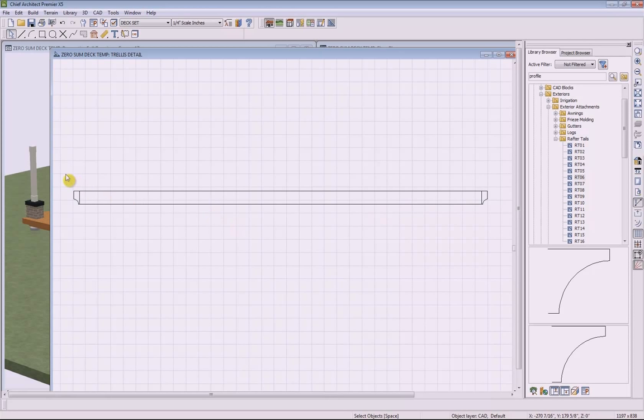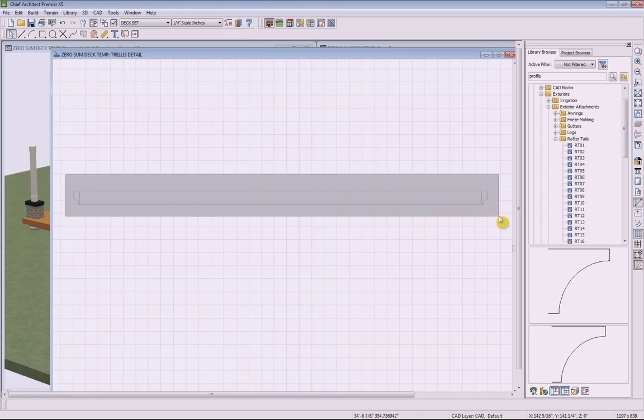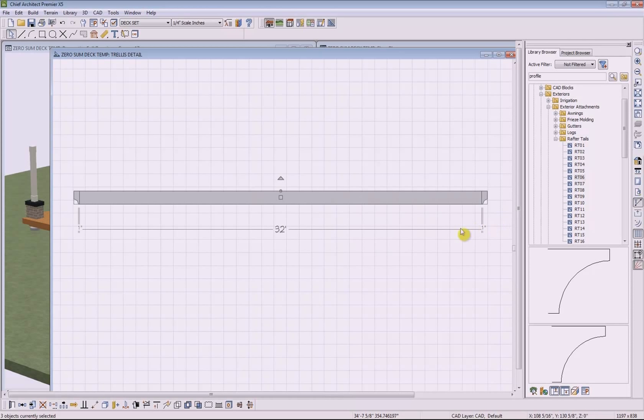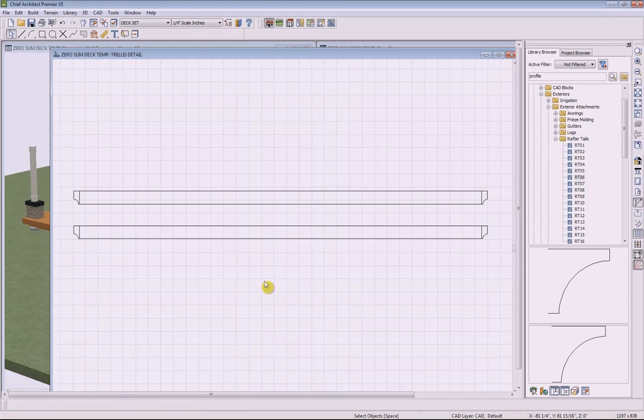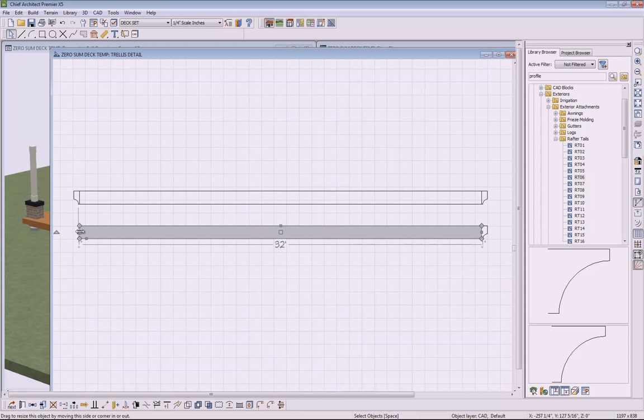and what I'm going to do is highlight and make a marquee around this entire beam that we've created, and I'm going to copy it and paste it in place, and I'm just going to pull down the replication of that. And for our trellis members, we're going to select on the end of that and delete one of those. And let's go ahead and perhaps we'll resize that overall. Let's maybe make it 10 feet. Okay.